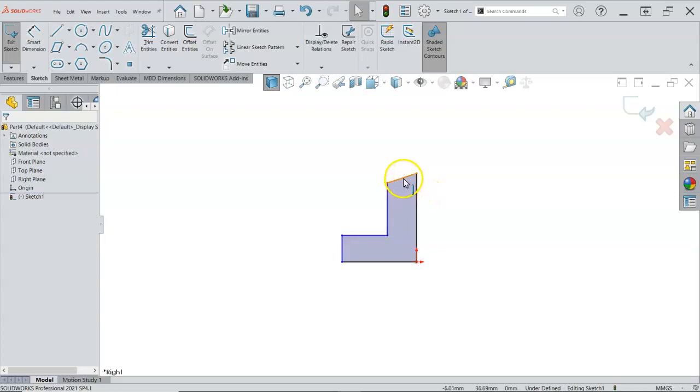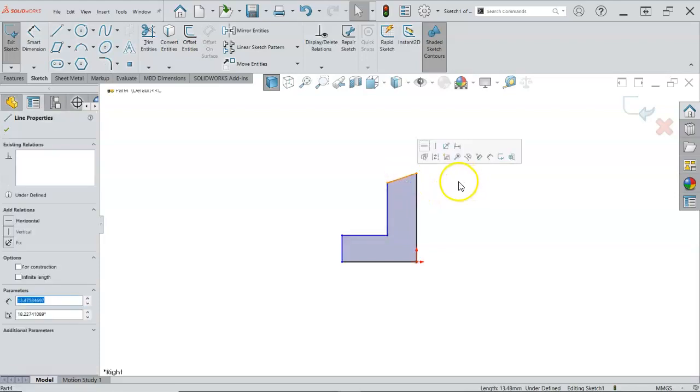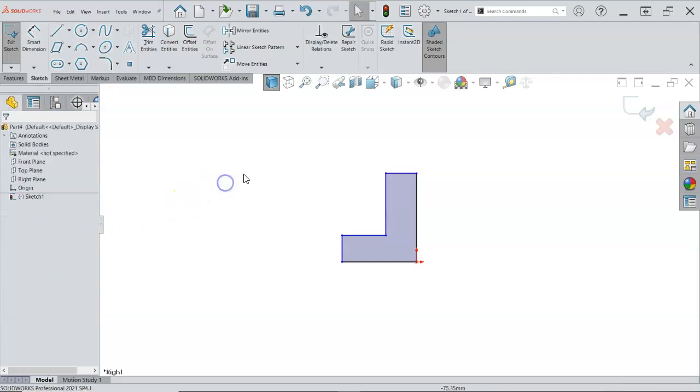All right, so let's fix this one since I missed. And on the pop-up, I will see horizontal. So just clicking on the line, selecting the line, will take you in to make horizontal. Or over on the left, if we miss that little pop-up, there's kind of a little pause. If you move the mouse too quick, you won't see that little pop-up window, in which case you just come over to the property manager and tell it that it's horizontal.